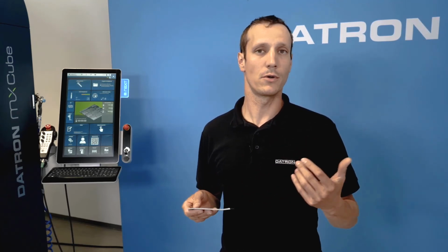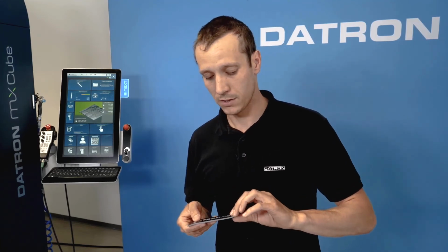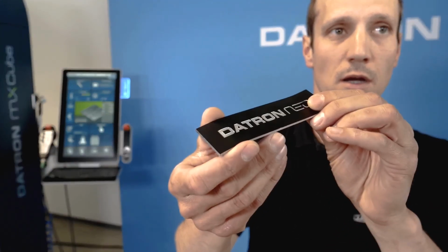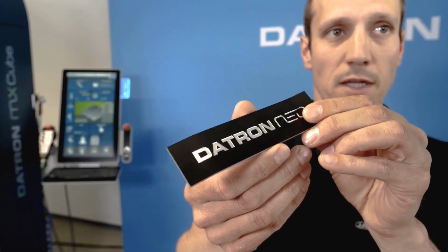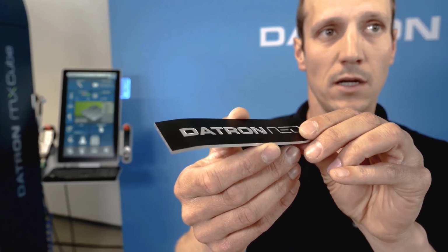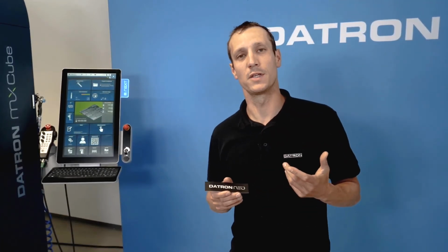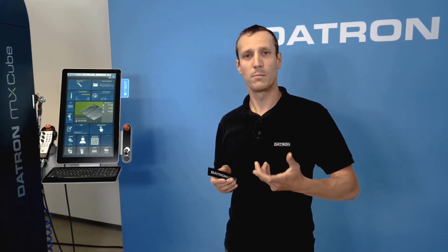And let's say you program a contour or an engraving 1/10 deep, it would just follow this shape and give you a perfect engraving on this. So this could be really helpful if you often have materials that have big tolerances. I think especially in plastic materials, this could be a real issue.